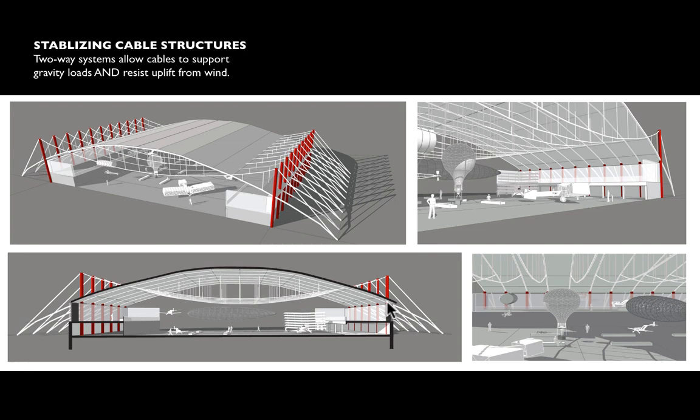Remember, in most tension structures, we have a compression structure that's helping it to do the work. And then here you can see the backstays that are both holding the masts up and then transferring the weight of the roof through the tension in the cable all the way down to foundations. But note too that the roof itself here has within it these cables that go in the other direction.